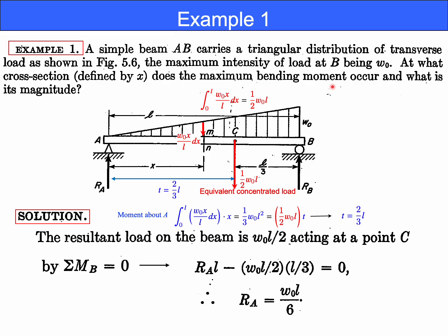In the present case, we can consider the balance of moments about A and B. Therefore, both reaction forces Ra and Rb can be determined by considering only the balance of moments at A and B. The moment balance about B is shown here.